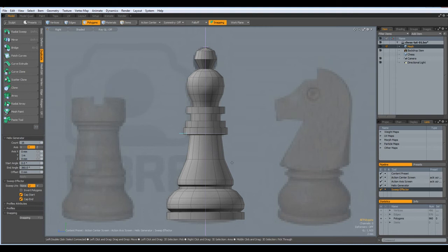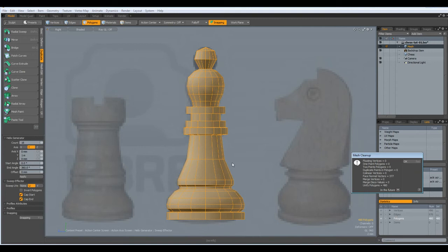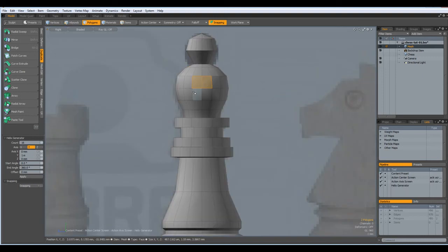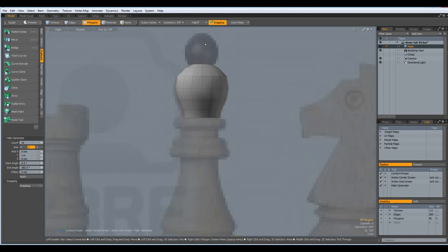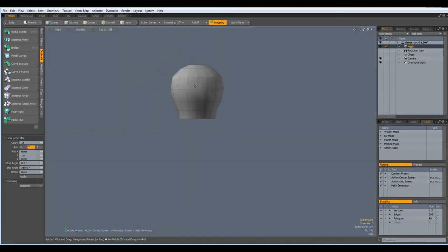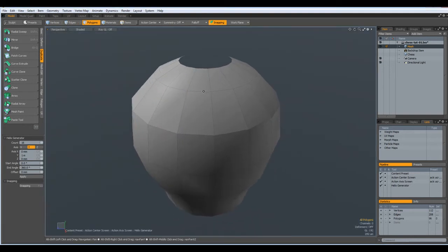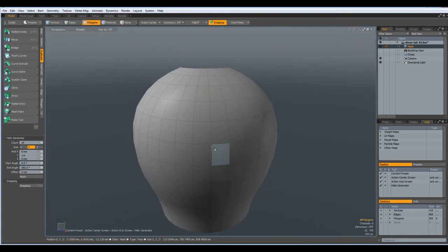I run mesh cleanup again, and it has removed 480 polygons. So next I select 2 polys in here, 2 in here, L key, Shift up arrow twice, Control X to separate this, Control V, and now we can select the rest and hide it. Okay. Now I get rid of the backdrop, go to perspective mode and press the D key to subdivide the model